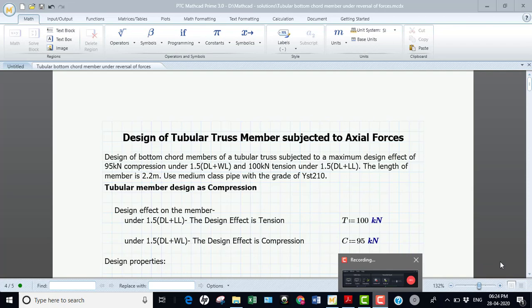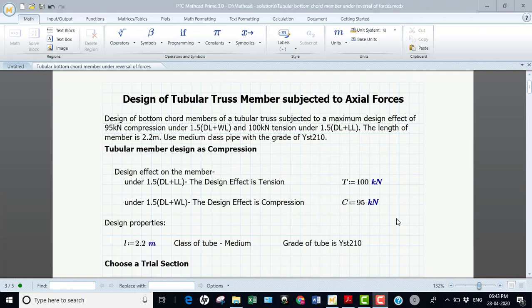After identifying the loads, do a load combination according to the standards. After identifying the governing load combination for the truss, do the analysis either by method of sections or using any software. From the analysis, you come to know the member forces of the truss members.